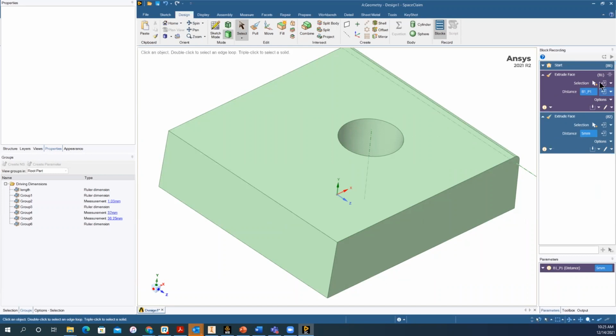If you did not have this functionality, you would be able to import your geometry, say, for example, from Autodesk into Ansys, but there is no way to keep updating the geometry parameters that you imported, because there is no history, there is no tracking. So you would just get the geometry at the very beginning, but you're not tracking any steps. So whatever changes you make in SpaceClaim don't automatically get updated.